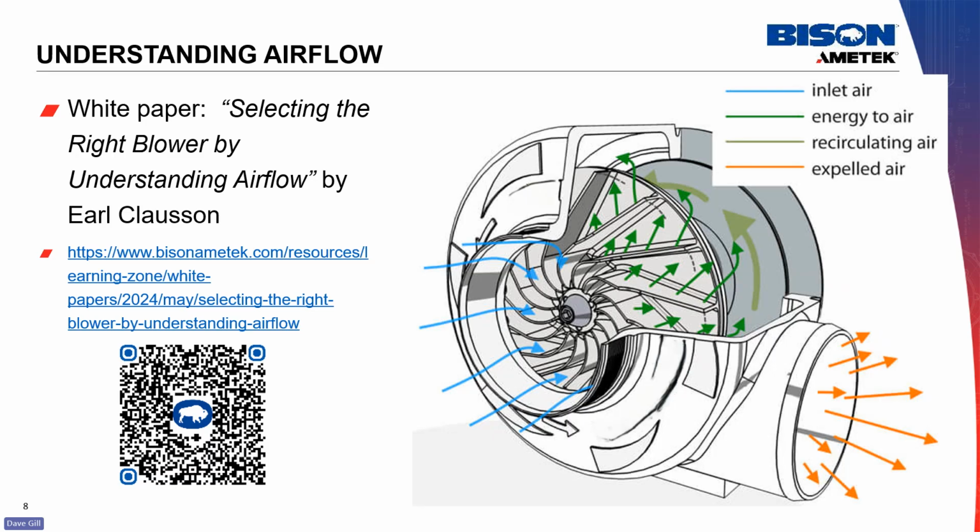Our blowers use centrifugal fans. Air enters axially at the center of the fan, and the rotating fan blades accelerate it in a tangential direction, creating a net airflow from the fan eye to the periphery of the fan where it exits at a much higher speed. This net flow creates a pressure differential across the fan, and this pressure can be used to do work, transporting dirt from a floor to a container, moving a fluid like paint or a material like plastic pellets, or just moving air to remove fumes or to dry your dog.